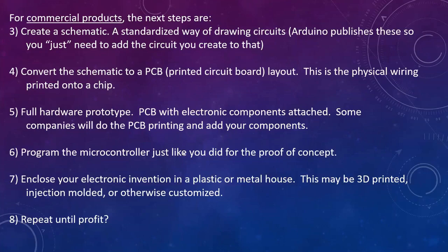Once you get something back from the company, what it's going to look like is almost something like an Arduino. It just doesn't have any of the parts that you don't use. It's just the parts for your circuit. And then you would program it the same way you would an Arduino, plug it into USB, download your program, things like that. And the last step is to create some sort of an enclosure.